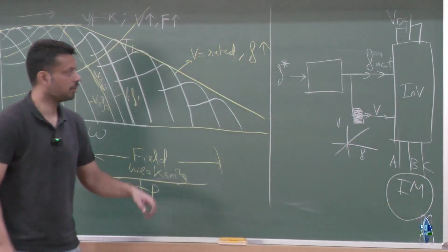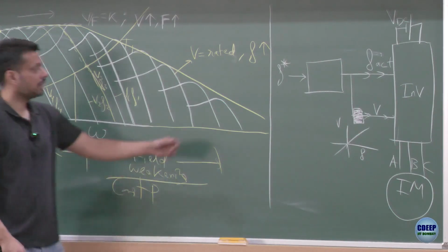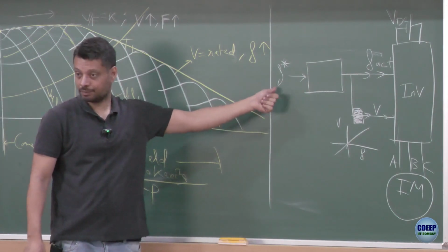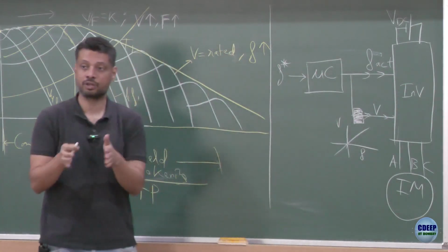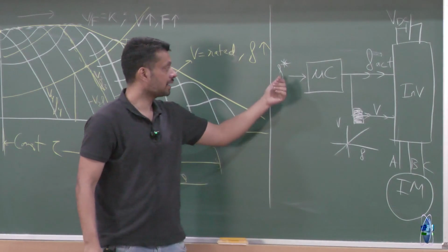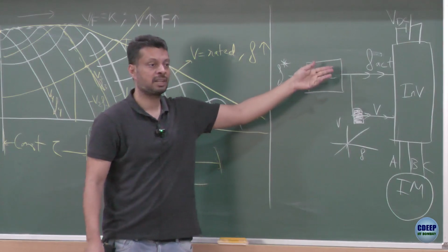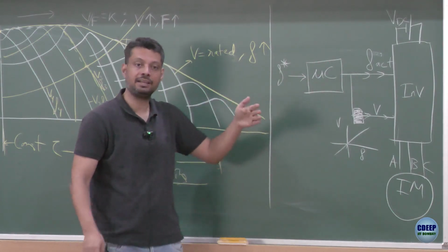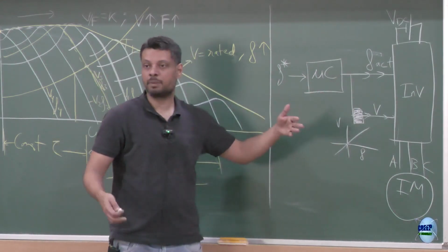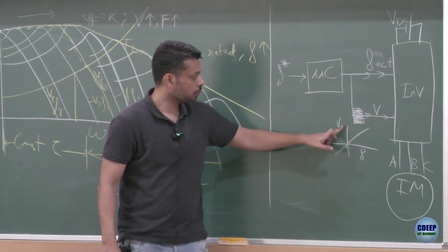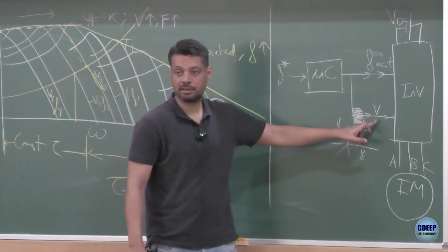So this is roughly what was happening in the drive that we were using in the lab, right. You were setting a reference speed or a reference frequency f star. There is a microcontroller sitting inside that motor drive, which, based on the command, would generate an actual frequency command. That actual frequency command in the beginning would be much smaller and then slowly it would increase and eventually settle to this f star. Since V by f has to be maintained constant, once the frequency is there, you do V by f, look at a graph, it could be a lookup table or a multiplication, and you get the voltage reference.